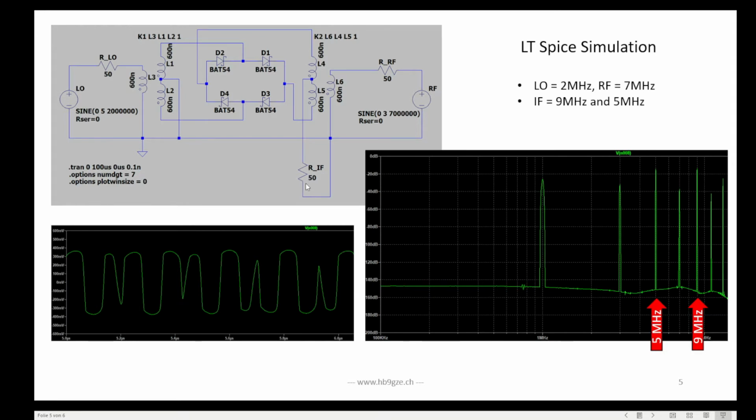And this is really a tricky thing. You have to make sure that you have a perfect impedance matching over all these frequencies at the output. Not only at your desired frequency of interest, in my case at 9 megahertz, you should make sure that you have a broadband matching of the intermediate frequency. Otherwise, you get reflections back, and the reflections get mixed with the input frequencies again, and the signal goes back and forth, and you get all kinds of unwanted spectra that you don't really want.